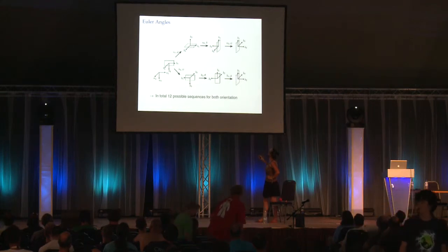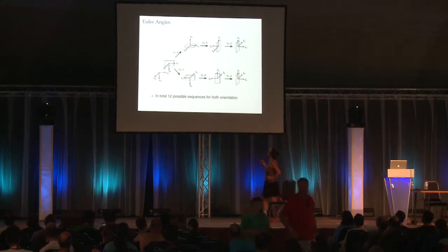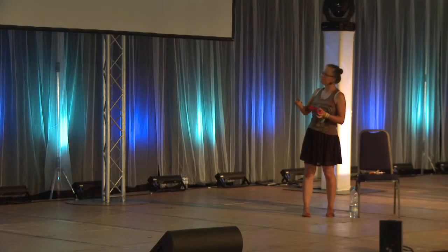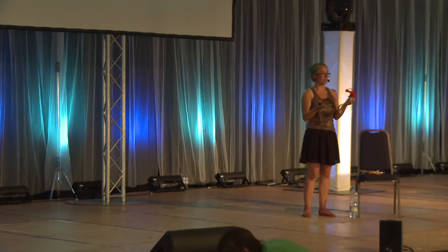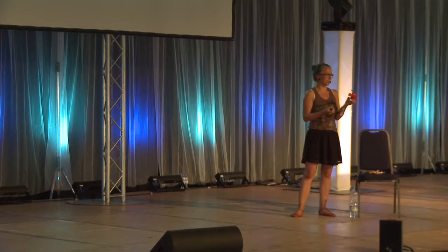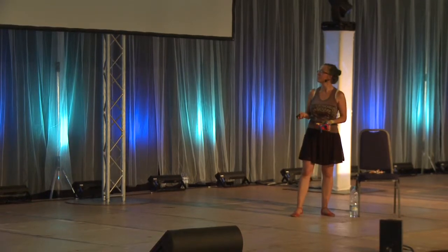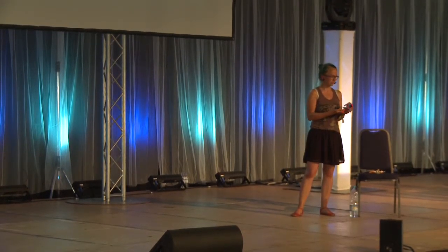It's a pretty obvious and straightforward approach. So the top line is the ground fixed frame, and the bottom line is the body fixed frame. You roll by minus half of pi, you pitch by half of pi, and you yaw by pi, and then you turn your helicopter. But that sequence is of course not unique. You can rotate pitch first, yaw first, and then do all the other stuff. So you just choose one sequence out of the 12 possible ones.